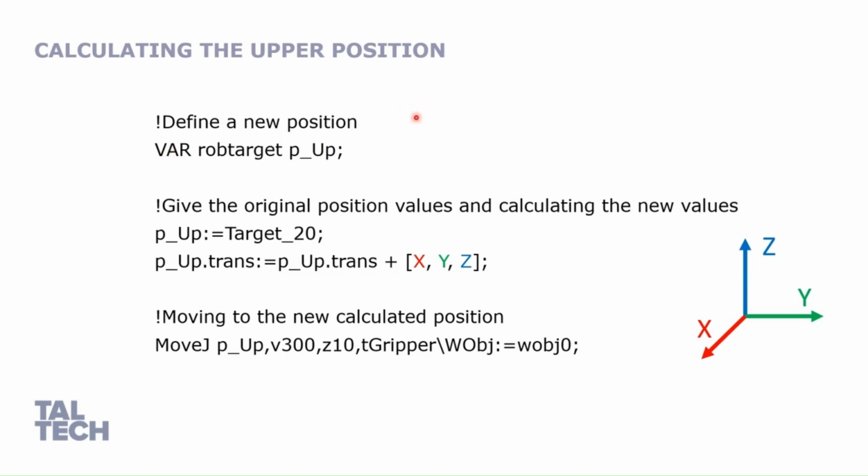So we define this new variable, then we add the position for picking, and then we do this calculation here, which allows us to shift the position up. For the shifting, as you can see, we have this X, Y, and Z direction. In our case, we want to move it up. I would say that we need to use Z direction for upper part. How much? Maybe 100 millimeters or 150 millimeters. Sometimes you can use less than this variable here. And in the program, then we go and use it like here. You can see this motion command itself.